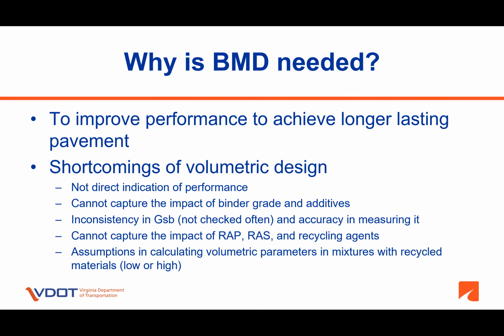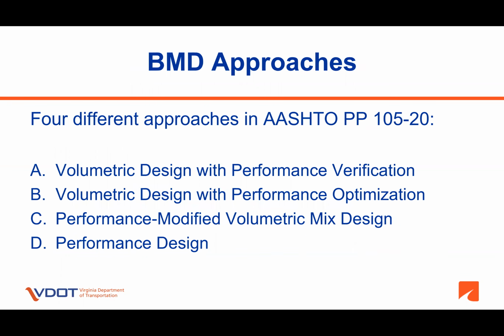I would like to add a caveat here that BMD is not a magic tool. It helps us have a good quality mix, but the ultimate performance will also depend on factors such as the condition of existing pavement and construction practices. If these are not optimal, we would not get the desired performance, no matter how good of a mix we design. As per AASHTO Spec PP105, there are 4 different approaches to the BMD concept, and in the next 4 slides, we will briefly go over these approaches.